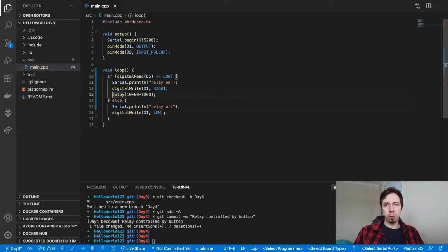The issue with delay though is that this is a blocking operation. So in our case, I think that could work. And it could actually prevent the situation where someone presses the button after 5 minutes, and then the waiting time is added to it. This is not gonna happen if we block everything using delay. However, this is not really a good solution for the future.